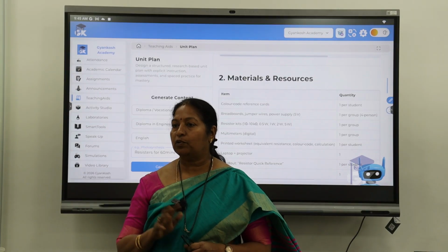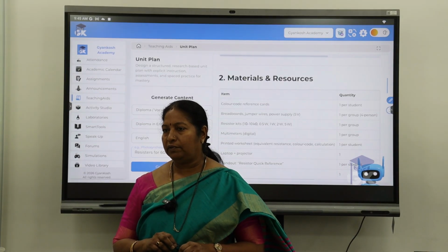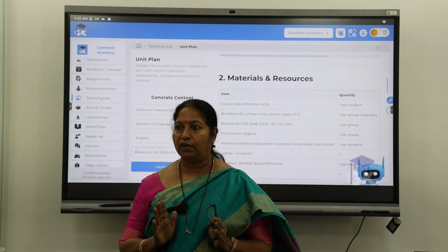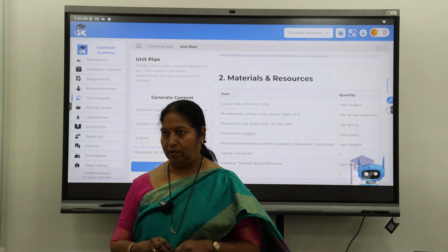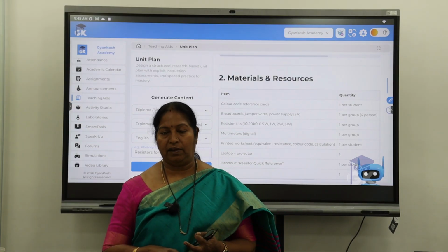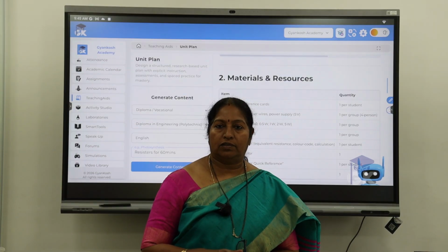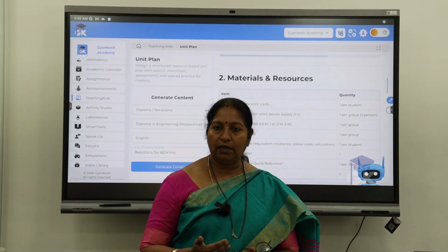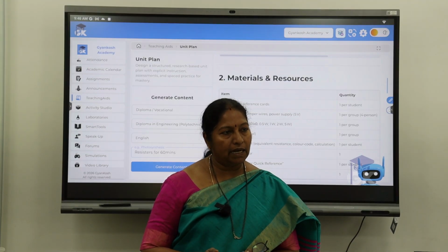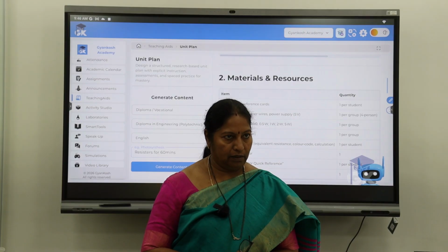That is the difference you can see in a multi-strand wire. Why do we use a multi-strand wire in electrical conduction for high voltage and high current? One reason is skin effect, which I'll explain when we come across it. The other is area of cross section. We know that R equals rho L by A. As the area of cross section is reduced, resistance will increase.